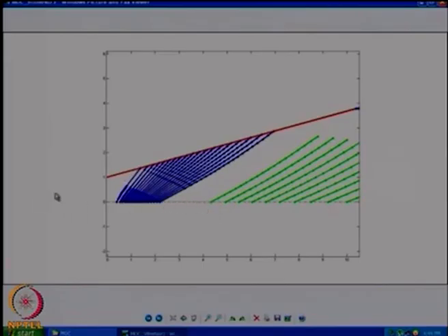Why? This wall is not a nice wall. It's not a well designed wall. Okay, this wall is such that it is going to give you compression after the initial expansion. So it's slightly decreasing, but not very much. They are almost going parallel in here if you think about it. And this gap will always exist. It is going to propagate all through your flow field. It's going to keep on propagating.